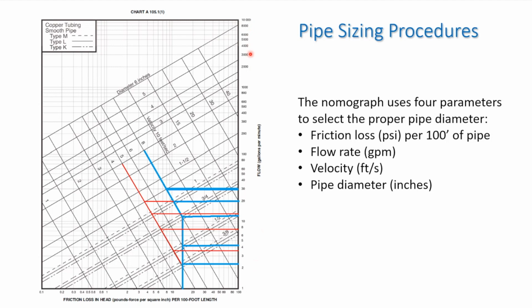This is where the water demand calculator, or if you're using Hunter's curve, the fixture unit method, the peak demand estimate will use the y-axis on the right-hand side. And in the interior, you have diagonals: your upper to lower diagonals are your velocity diagonals, and your right to left diagonals are your pipe sizing.